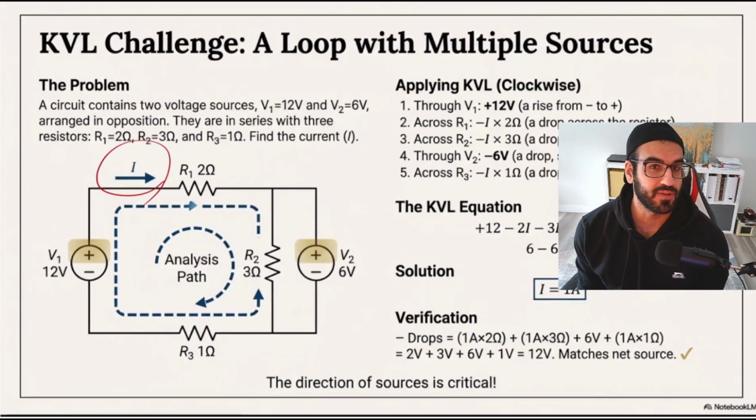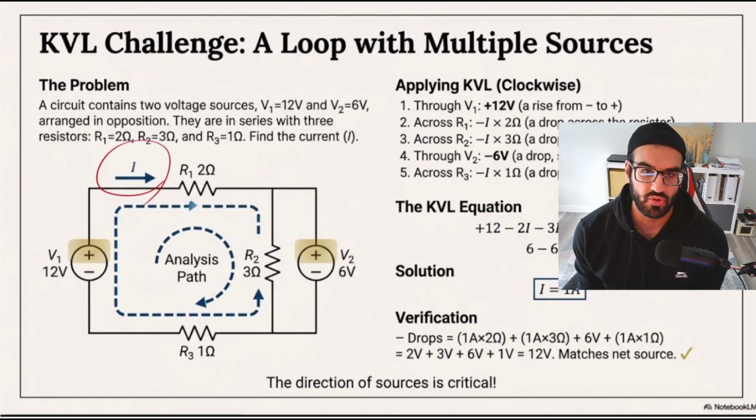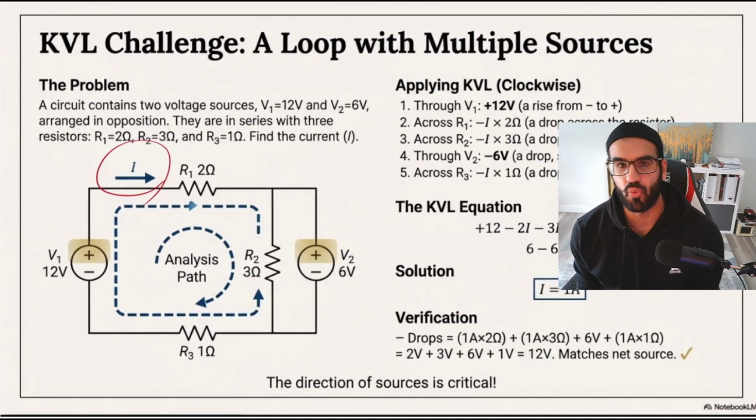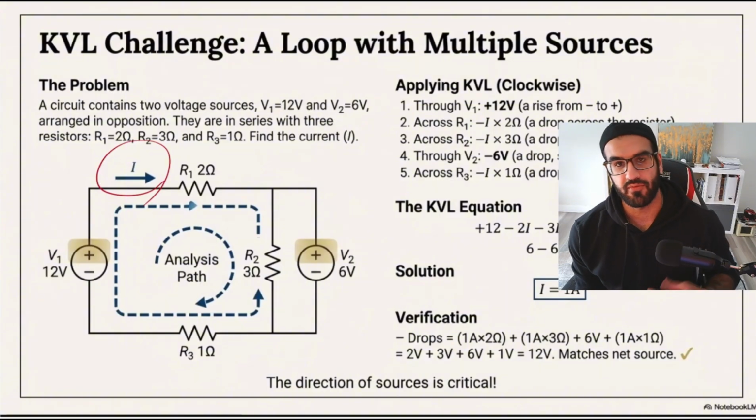Then find the specific value, could be current or voltage, based on only one source, and then stop that specific source that you had and move to the next source. Still do the same procedure that you did for the last one and move it forward. After that, try to decide about the direction. If all of them were aligned with each other, you have to add them up. If they have some problem, you can subtract. But at the end of the day, this is one of the theorems that we were talking about, and we do have one video related to that. So at this point, we are going to use the KVL.